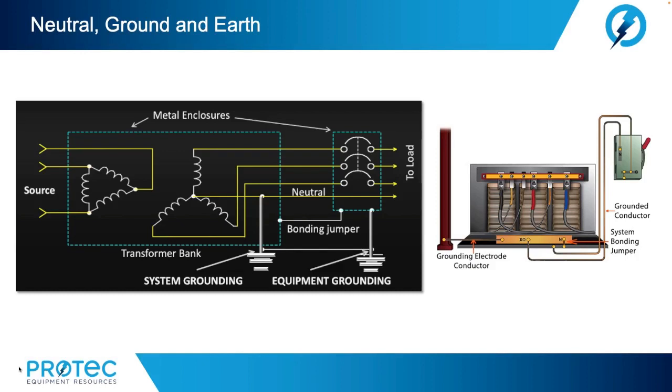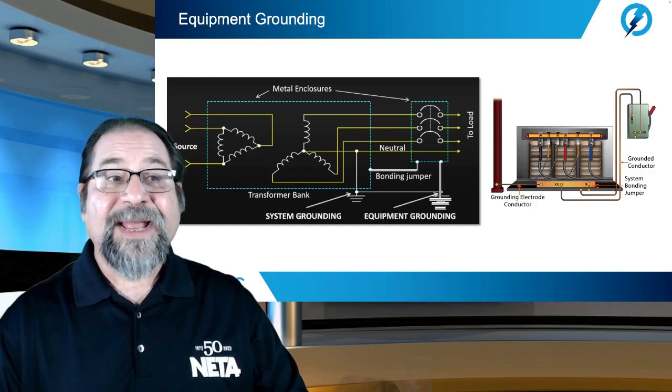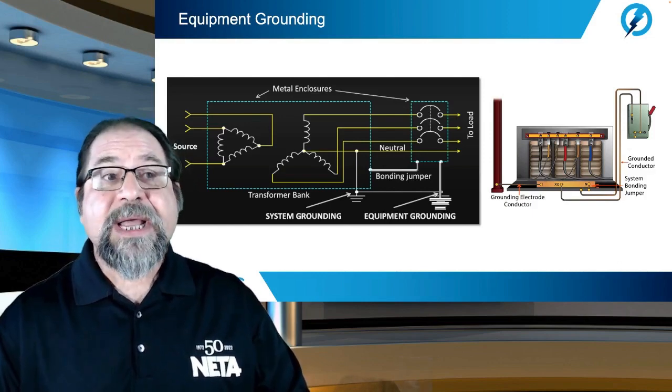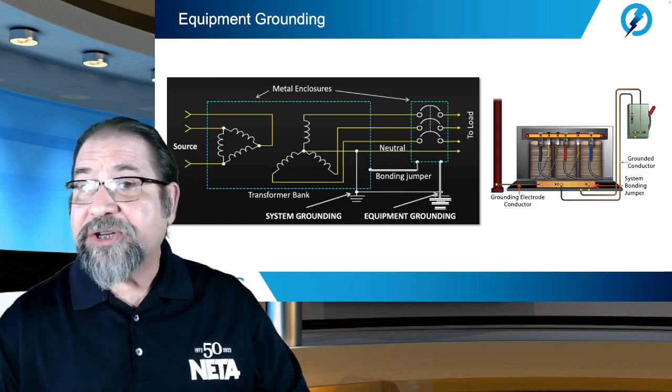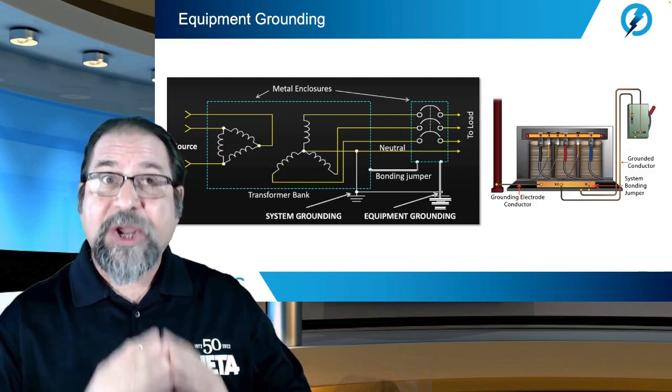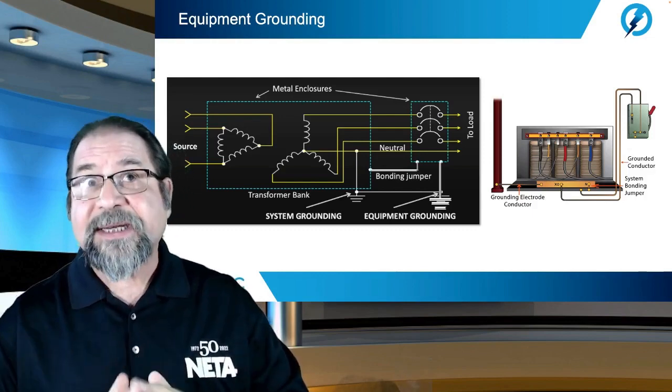Under normal conditions, a grounded conductor does not carry current. Grounding is an integral path for home wiring also because it causes circuit breakers to trip more quickly, which is obviously safer. Adding new grounds requires a qualified electrician with information particular to a power company distribution region. Now, the term grounding is commonly used in the electrical industry to mean both equipment grounding and system grounding.